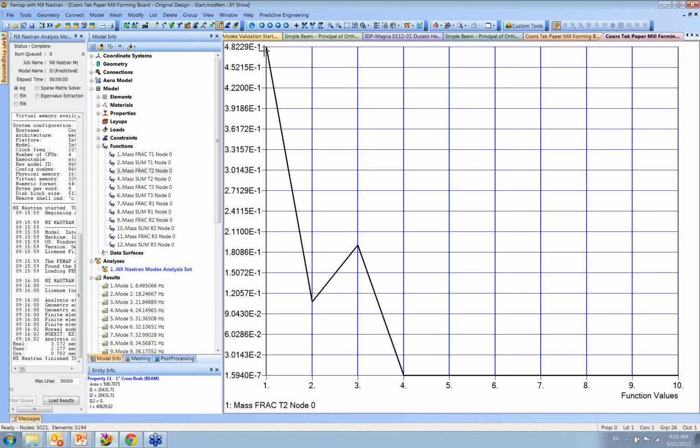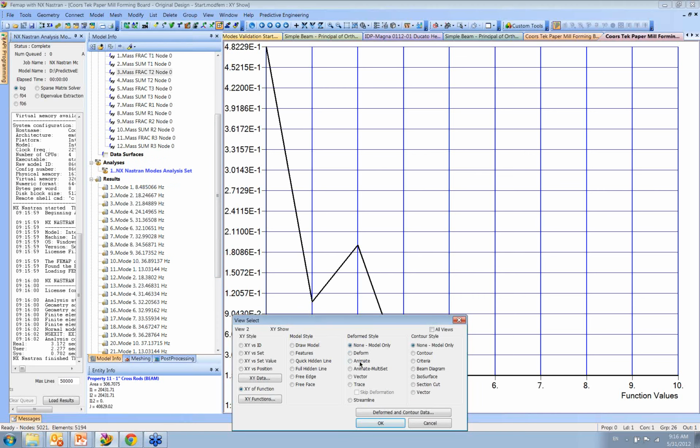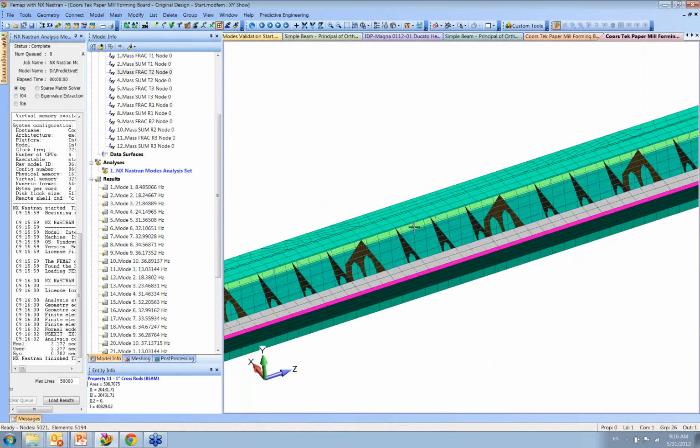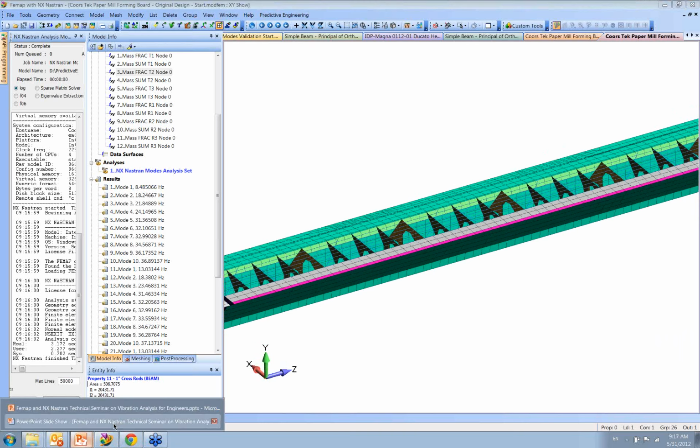You're close at 48%. And that is why the first mode was so important on this structure, because it had so much mass at near 50%. And so of course once that first mode got going with all that mass, it just tore the machine apart. So this was a real design. Actually, that's the way they went forward with everything. But what I like to say is it really shows that there's just no way an optimization program would have figured out to put a rod in there like that. And I don't even know how you would start, because the structure has so many design constraints and design requirements, whatever you would do with it.